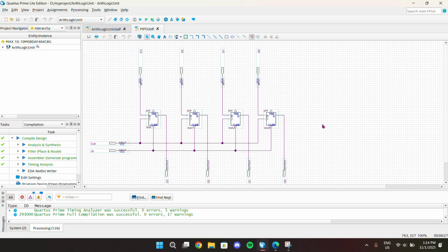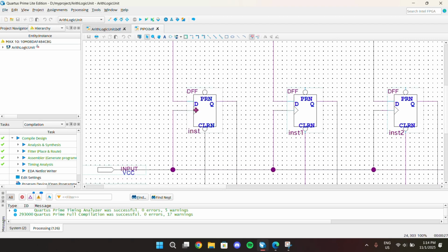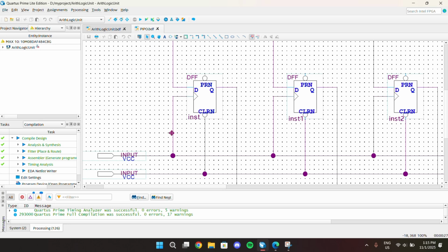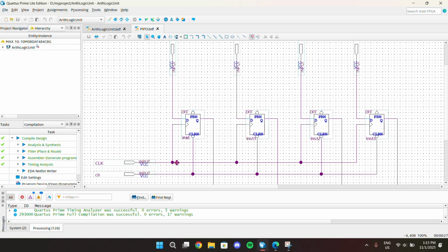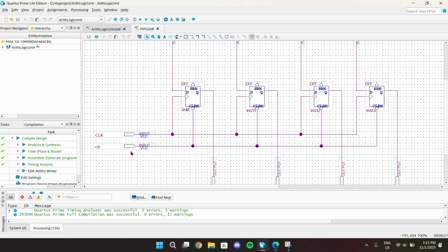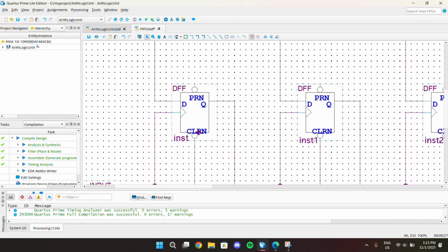So what the PIPO register does is it acts as a storage unit, and you can see here it is a positive edge trigger, and there is also a bubble at the clear input. Whenever the clock shows a positive edge rise, the D flip-flop activates, and when the clear input is 0, once it gets to here, it becomes a 1.